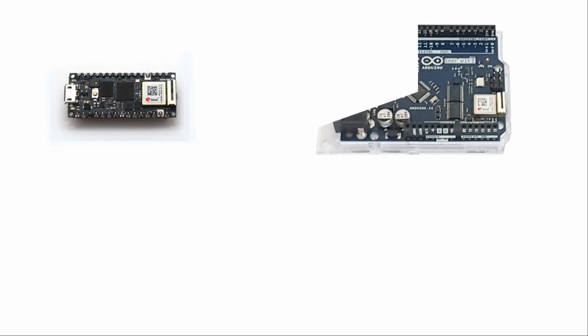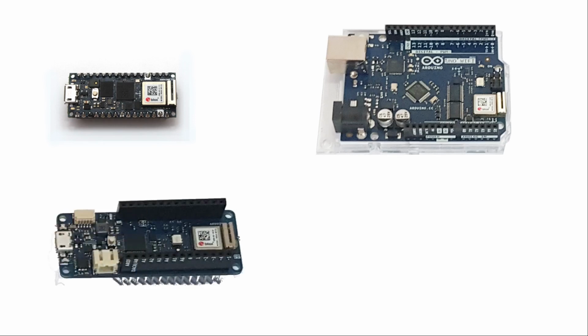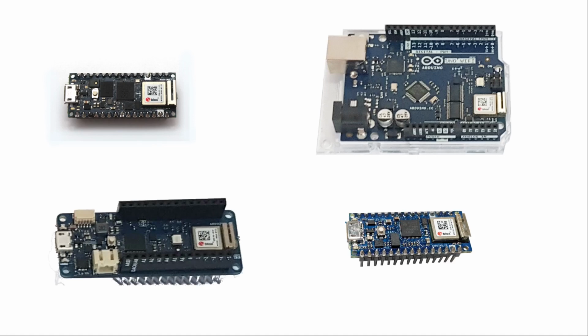It won't work with all Arduino models. As this is a wireless project, it does need wireless capability. Specifically, it needs to support the WiFiNINA library, which should include most of the Arduino IoT models. In addition to the Arduino RP2040, I've tested with the Arduino UNO WiFi Rev 2, the Arduino MKR WiFi 1010, and the Arduino Nano 33 IoT. When I come to the PCB, it will be specifically for the Nano format, but you should be able to use the code with the other models.